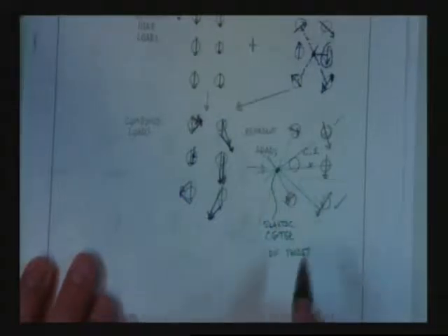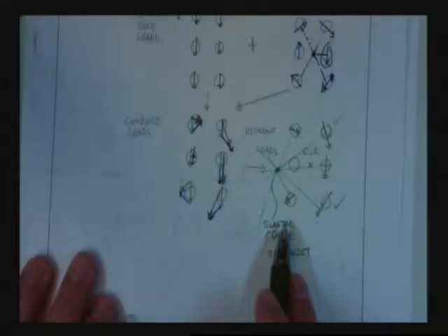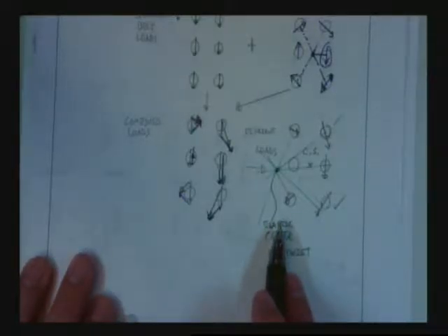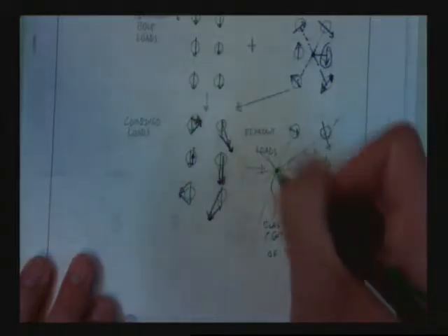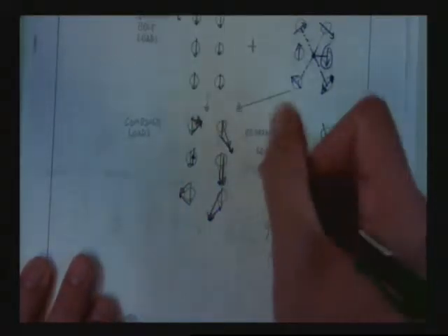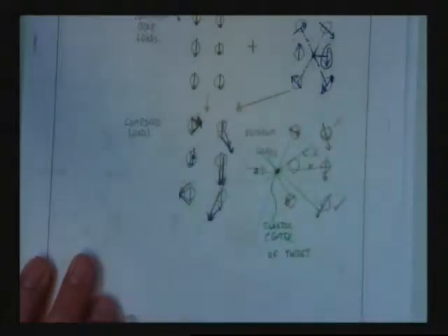And we're going to find out when that happens that a lot of the assumptions that went into this problem are wrong, and things will change. If you've maybe seen this in the past where you talk about the neutral axis, the elastic neutral axis, or the centroid of the member, and then you have something called the plastic neutral axis, that's the point where things bend about right as they plastify. And they're not always the same place, right? And we're going to find out in this problem that just because we have an elastic center of twist, we're also going to find something like an inelastic center of twist. They're going to move.